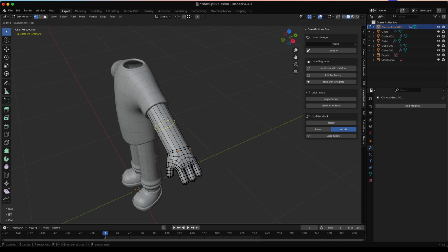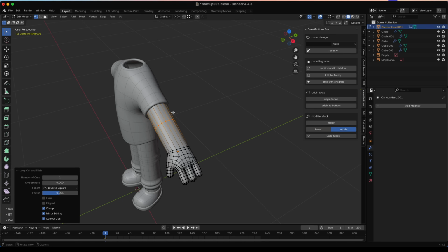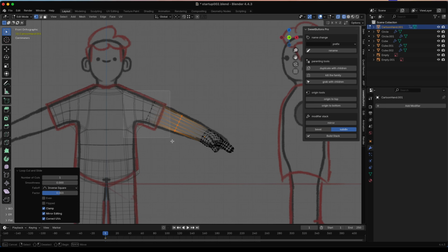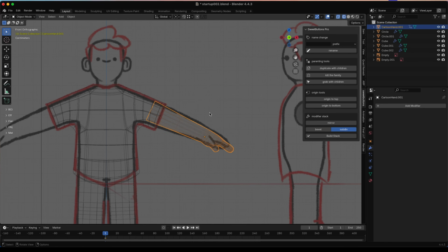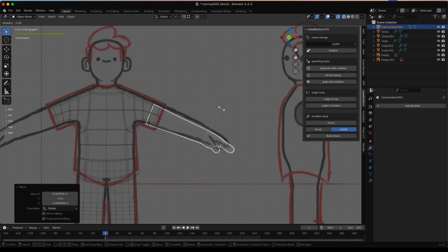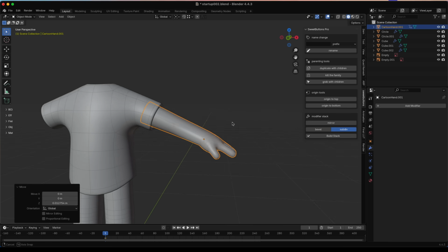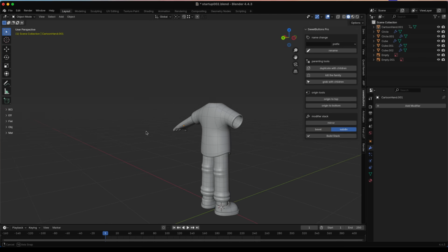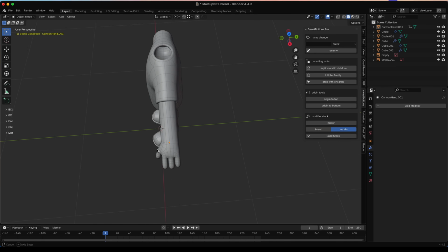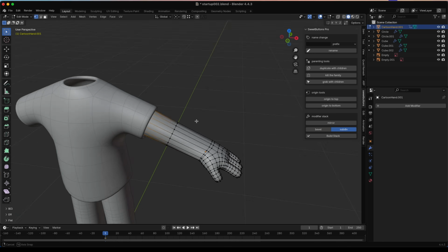So let's go ahead and add in another edge loop. Now we can use that trick we talked about previously with the E and F. And I'm going to orient it to this top piece here and just click to confirm that. And I can grab the top here, and I can make sure this is circular if I really want to dial that in. I'll again kind of change its placement there. And honestly, our arm is looking pretty good. It looks appropriate size. It's not kind of flanged weird, and I think that's going to work.